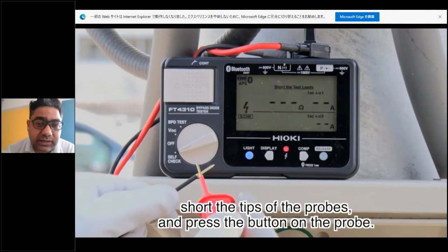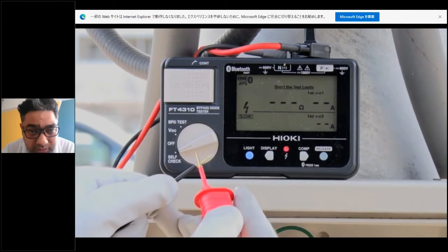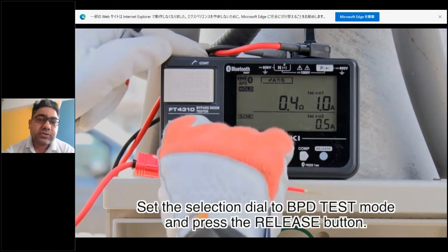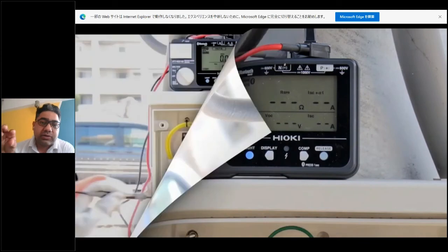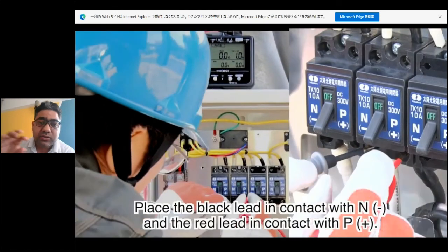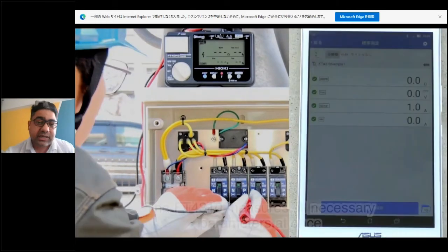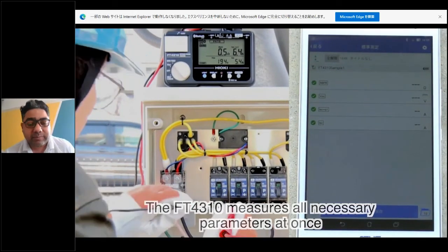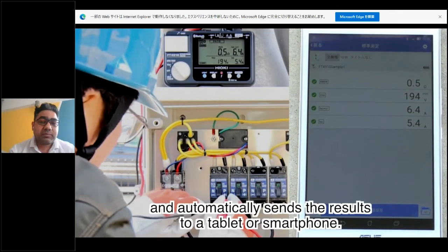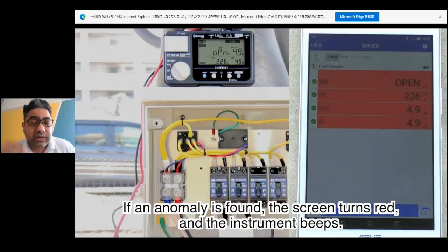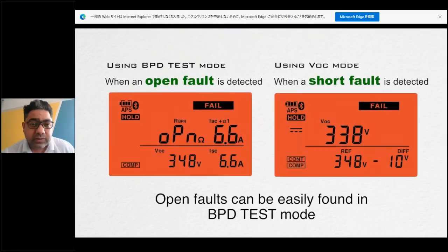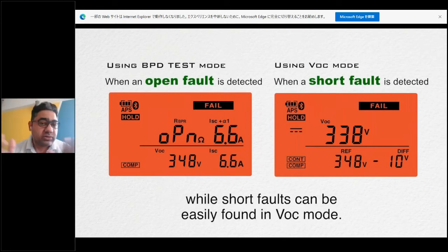Like, assume there is a panel which has 30 volts. If we divide it into three parts, then each series of cells has 10 volts. If one particular cell of any series is not working or is behaving like a resistance, then my whole panel will not work. So the bypass diode bypasses that series of cells, and then at least we can get 20 volts from that particular panel. That's how the bypass diode works. Now I'll come to the next phase.